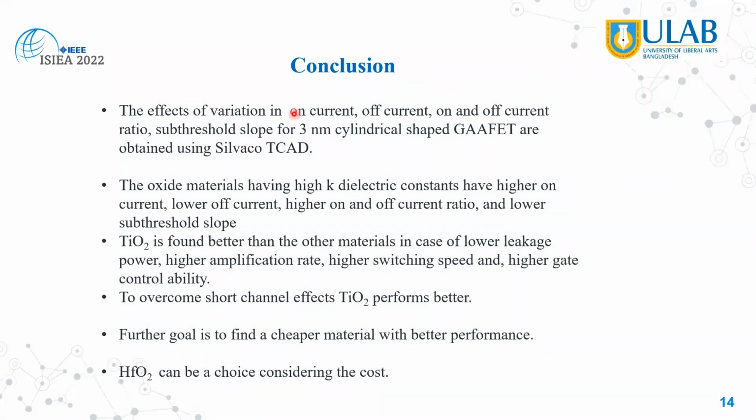Moving on, this is the conclusion. So the effects of variation in the on and off current ratio and subthreshold slope or swing for the 3 nanometer cylindrical-shaped GAAFET are obtained using Silvaco TCAD in this work. The oxide materials having high-K dielectric constants have higher on current, lower off current, higher on and off current ratio, and a lower subthreshold slope.